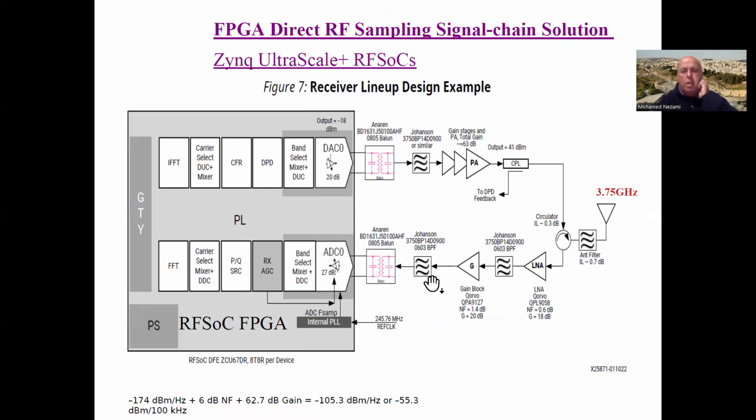They gave you the devices. This is 3.75 gigahertz. Very much just like the ADC, you need the intermediate path between the ADC and the antenna, and it's directly connected, as you can see. There's nothing but amplifiers, low noise amplifiers, filters, and then a balun in there.